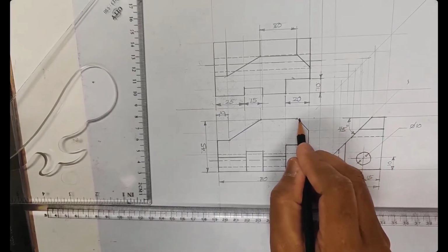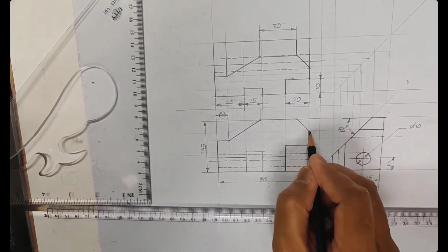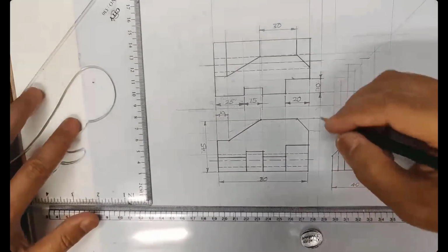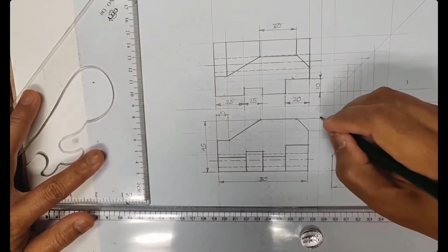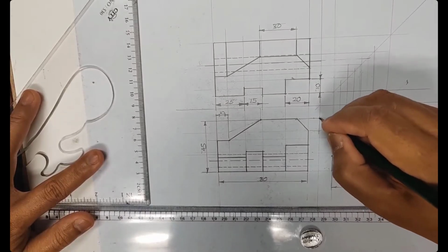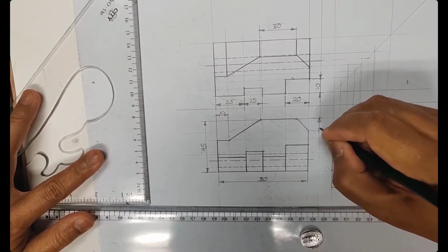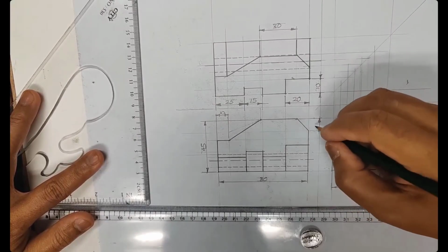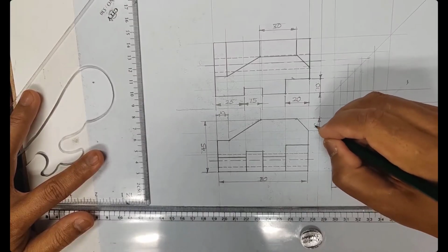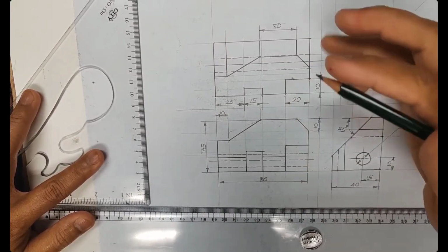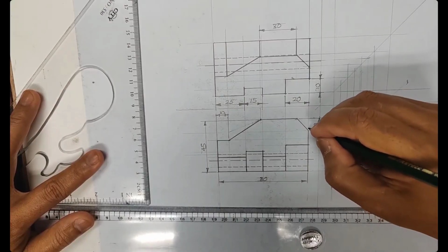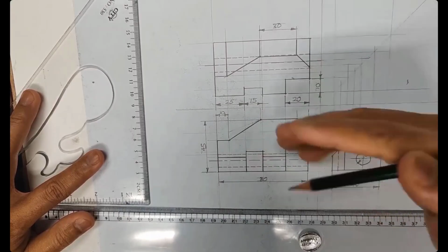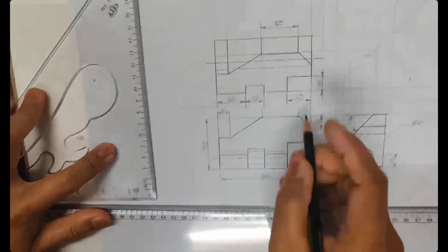Use a ruler, with a gap, because this front view clearly shows the features of this chamfer 10 by 10. So you have the extension line, and a dimension line like this, right? Solid. This dimension line has no gap there. There's a gap. So this one will be 10. Guys, I need to be quick. I'm doing it by hand. So at this corner, a gap, make the extension line here. Not too close, about 2 letter height from the level.